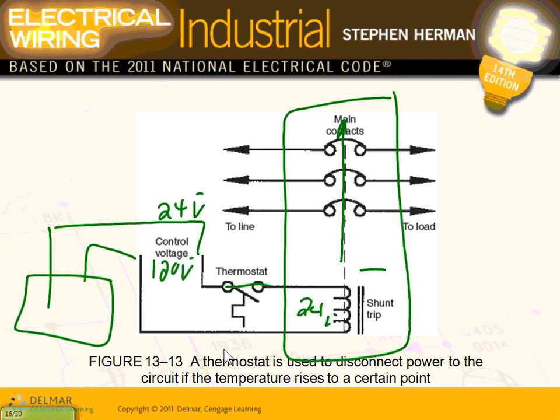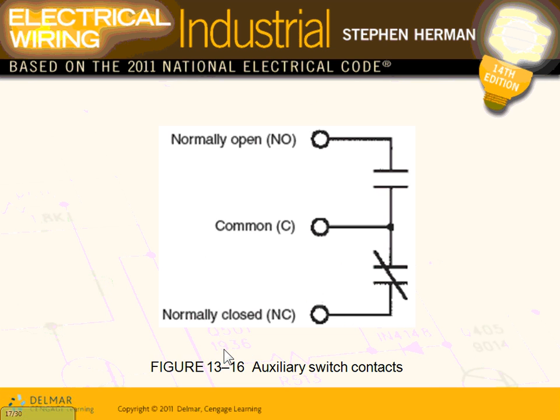Tripping it is easy. Turning it on, you need to have a motor that can wind it, especially big circuit breakers. When we went to EMI, remember how he was charging the circuit breakers when he closed them? You have to give it a couple of hits to charge them, and bam, it closes through a spring. Either you charge it manually through a spring, and then it closes, or you can actually energize a motor, and the motor charges the spring. When it has enough energy, it flips these contacts closed. Shunt trip is remotely turning off a circuit breaker. Not a contactor, a circuit breaker.